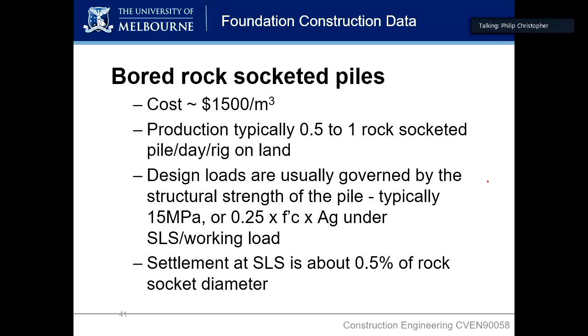Now, typically, a rig and team might do, if they're going pretty well, one rock socketed pile in a day. If things are going a little bit slower, maybe half a pile in a day. So it takes time. And it takes time because you're digging a bit of soil, bringing that up, putting it off to the side and dumping it on the ground, then putting the rig back in the ground and drilling out another little bit. So you've got to think of it as a really iterative process.